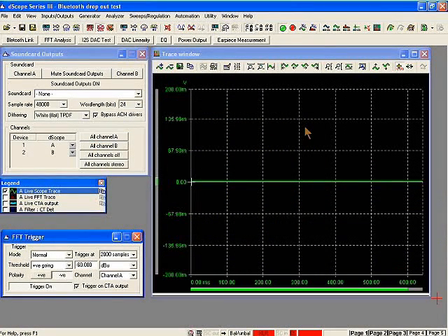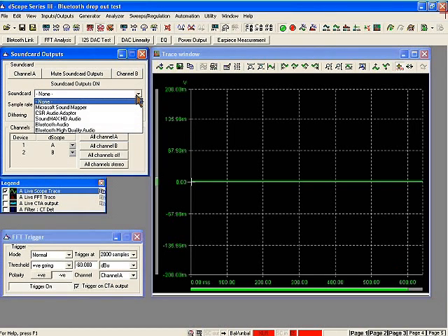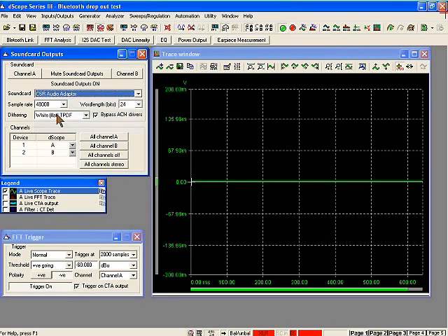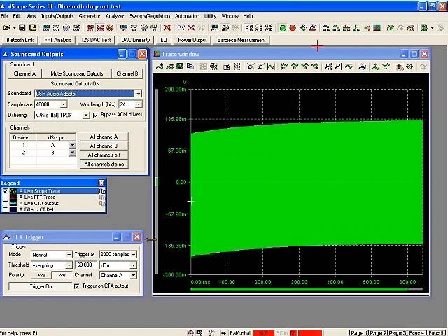And what I'm going to do is I'm going to assign a Bluetooth audio dongle as my output device from my test system. So this here, the CSR audio adapter, is a Bluetooth transmitter, a Bluetooth dongle. And I'm going to assign that as an output device from my test system. I'm measuring the output of the receiving end of the Bluetooth system, and I'm currently showing you the live waveform of the output from that device.